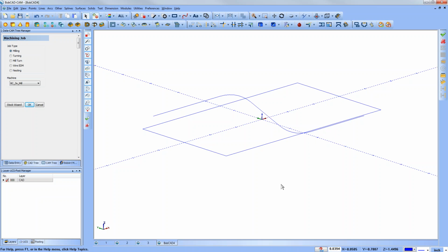Right, so in this part here, I'm going to try to use the split command. Split solid is used to separate a solid body using a splitting surface. For this function, I'm going to select a single solid and one splitting surface. The software is going to automatically create multiple solids from that, as we saw in that initial image. Just note that the splitting surface has to completely go through the part, so it can't be within the part. It's definitely got to go past the bounds of the part. Think of it as something slicing all the way through. It can't slice halfway through.